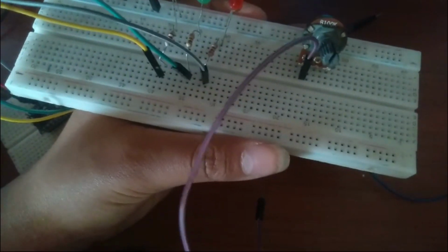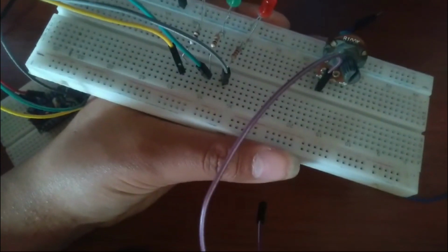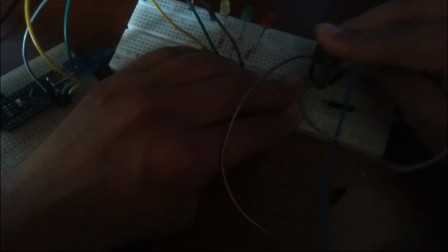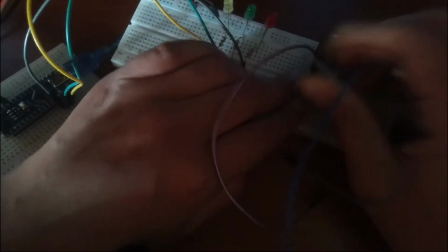as the LEDs, because if the protoboard is too large, maybe you will find two divisions, a division between two sides of the power supply bus, right? So for that reason, ensure that the positive and the negative of our potentiometer go to the LEDs bus, right? So the positive we're going to connect in this part, and the negative we're going to connect at the same time, right? So once we have this, we have to verify the connections.